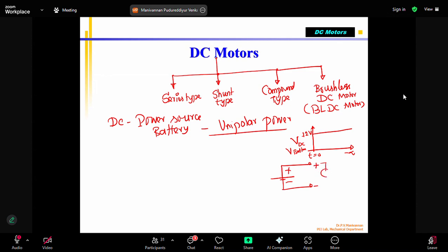If we connect a voltmeter, it will show 12 volts. For a lead acid battery used in cars, it is 12 or 12.5 volts depending upon the charge level. Theoretically, we say 12 volts in the fully charged condition. It can go up to 13.8 volts also, the maximum voltage that we will see when we talk about it. So the voltage remains constant, the height with respect to the x-axis remains constant, as long as I don't connect a load.